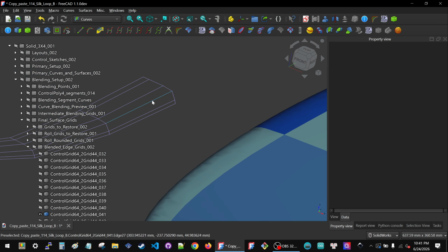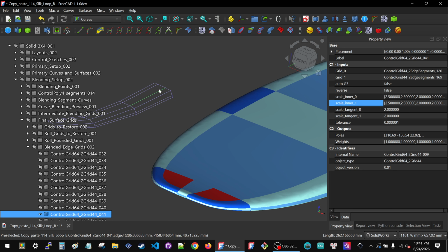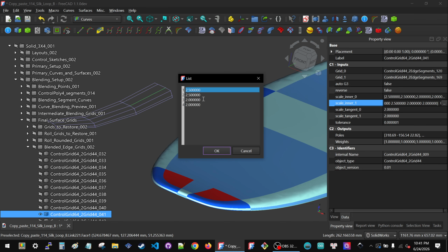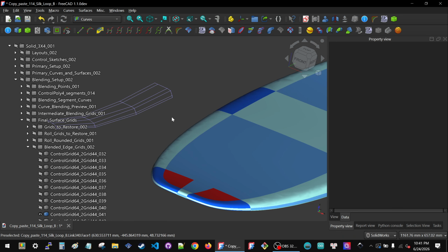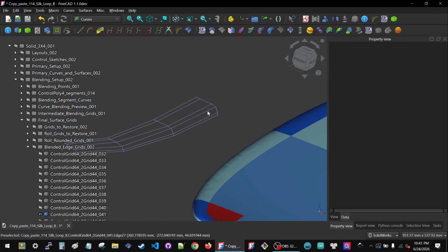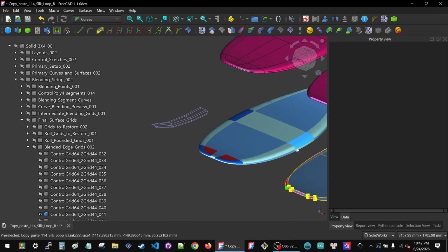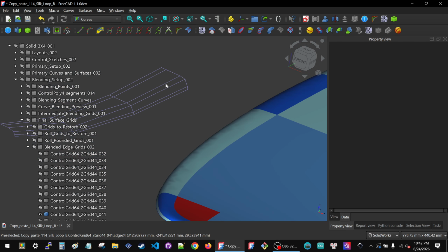And I can inch back and forth on this and get as close as I want. So here, I can't go any higher with this guy or it's going to create an upper ridge. But this guy here, I can keep pushing it. 2.75 did this much. Let's see, can I do 3? I don't think this is such a great idea, but technically, as long as you don't push these guys past each other and create a reversal, you could try to make this corner extremely sharp.